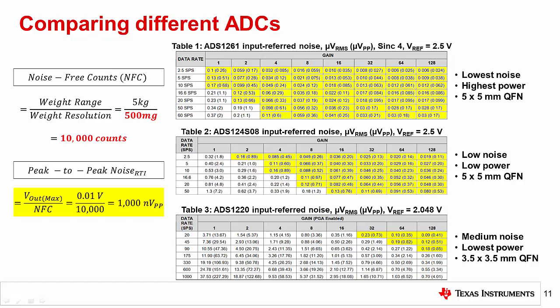Ultimately, you need high-resolution ADCs even if your target noise performance is only 15.3 bits, because the system actually requires low noise performance. That is why it makes sense to define system performance and choose ADCs using input referred noise.